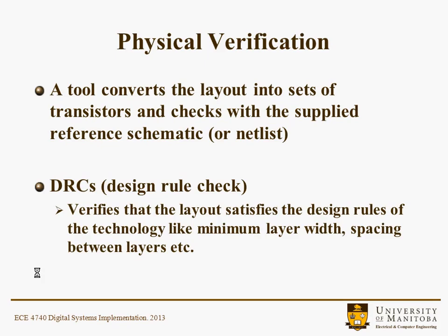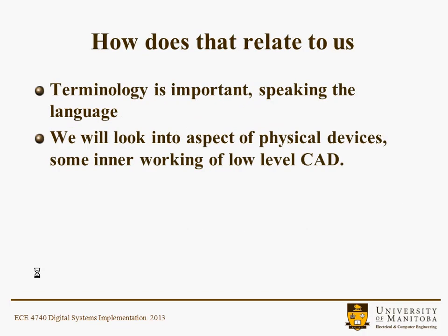So how does all of that relate to us? Well, certainly technology is important, and just being able to speak the language helps a little bit. In a fair bit of detail, we'll look into various aspects of physical devices and some of the inner workings of low-level CAD, and we'll spend a fair bit of time fleshing out some of the details, some examples of the clock tree synthesis, maybe some of the tool flow for doing that, static timing analysis, and some of the circuit techniques that you can use to ensure that your circuit is going to operate faster than it would have otherwise. It's always a design trade-off.